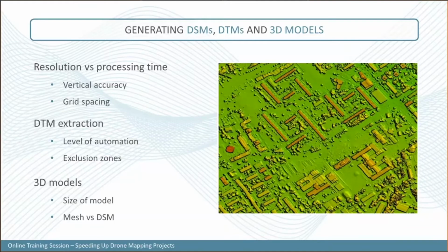From the digital surface model, we can then derive a digital terrain model. So we have an algorithm that, as much as possible, removes buildings, cars, trees, and allows you to auto-rectify your images on the terrain model. Sometimes this algorithm over-smooths specific features such as bridges. So you can use exclusion zones if you want to keep specific features in your terrain model.